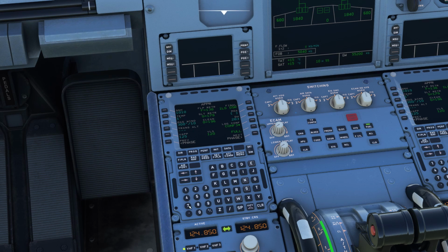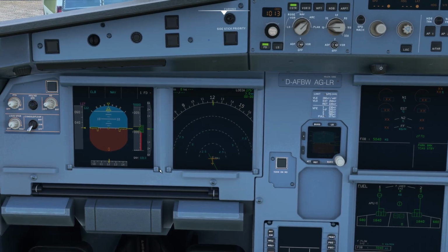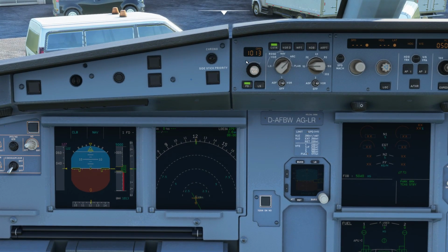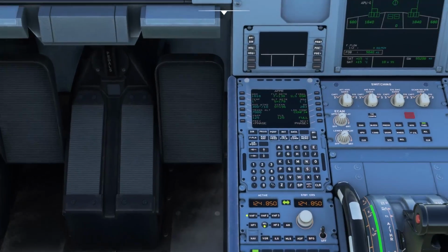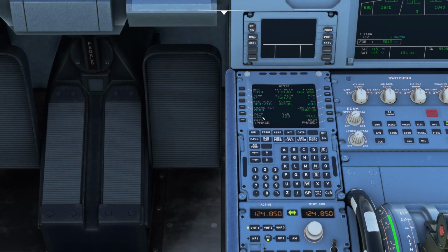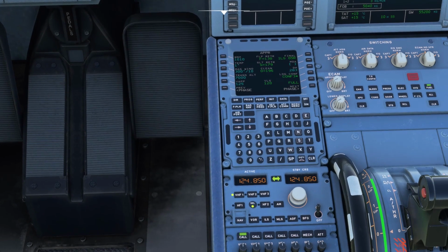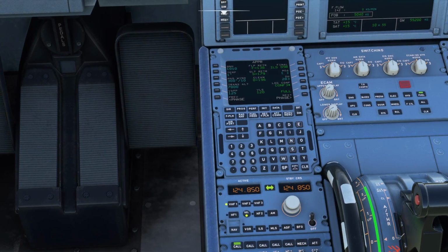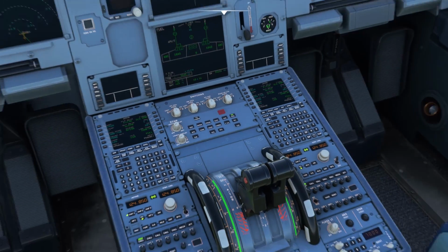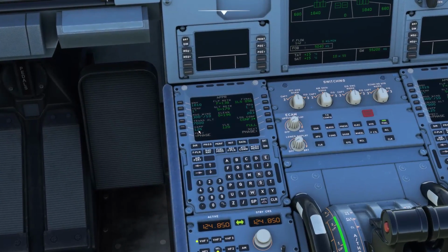Okay, transition altitude, again I'm going to go for 7,000, and that is the altitude where you transition from standard to local sort of QNH setting. Okay, and the VAP speed is the minimum speed that you want the aircraft to travel at when it's got the flaps full, I believe, is the basics of it.